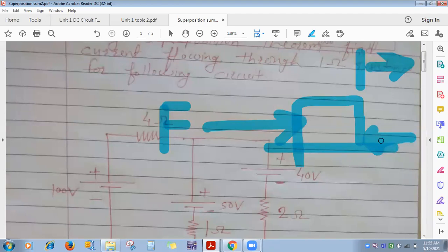Whenever you consider these non-linearities and analyze the system, the results will be more accurate, and that comes under non-linear analysis. But if you are neglecting the effect of temperature, neglecting the effect of friction, and analyzing the system, then that comes under linear analysis. So obviously, non-linear analysis, if you do, results will be more accurate compared to linear analysis.